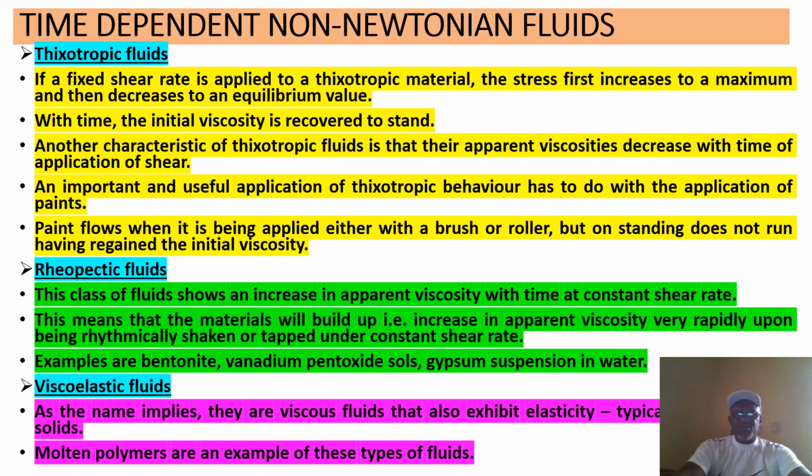Now, time-dependent non-Newtonian fluids. We have thixotropic fluids. If a fixed shear is applied to the thixotropic material, the stress first increases to a maximum and then decreases again to an equilibrium value. So another characteristic of thixotropic fluids is that their apparent viscosities decrease with time of application of shear.